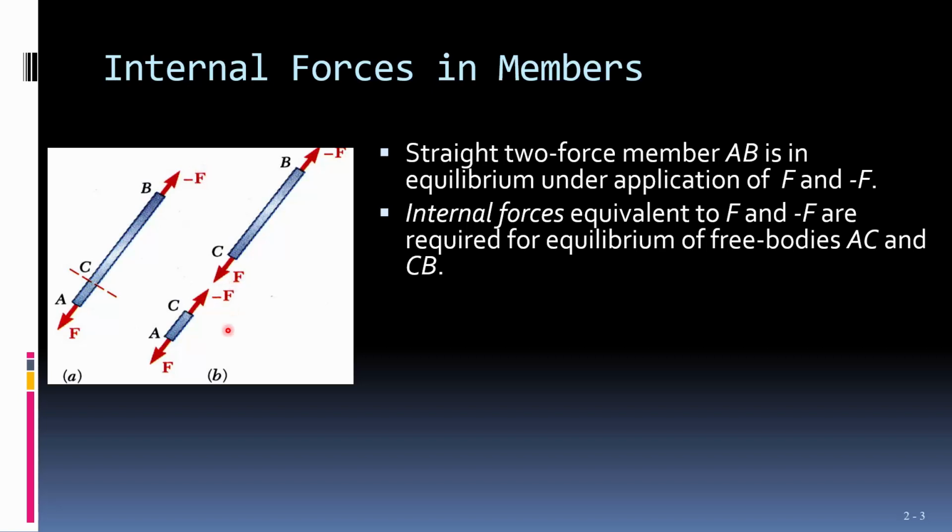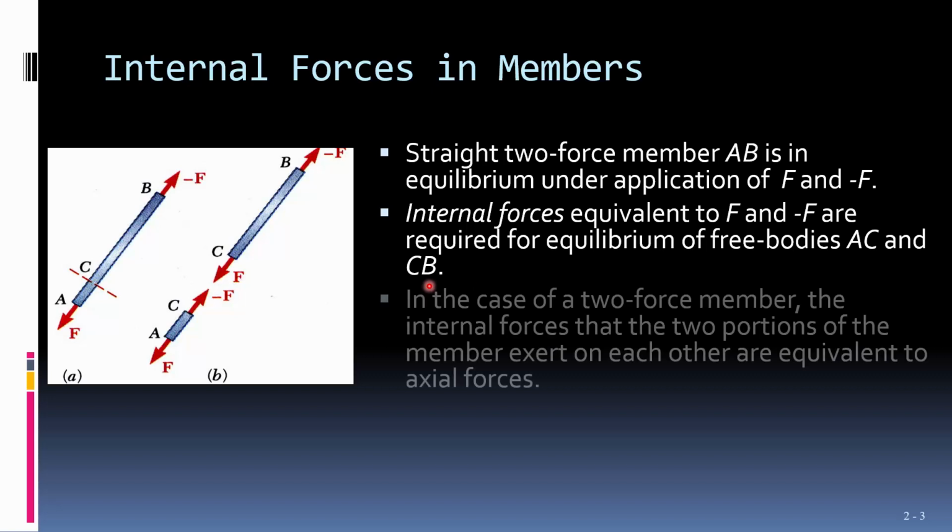So now let's consider this. Let's cut this at some arbitrary point C, right? So now it's cut at some point C. Well, you need these internal forces F. So if we look at this section right here, you have this external force here. Well, in order to keep it in equilibrium, you're going to have this internal force negative F. And this portion here has this external force applied here, but you have to have this internal force F applied here as well. So in order to maintain equilibrium, you have to have these internal forces.